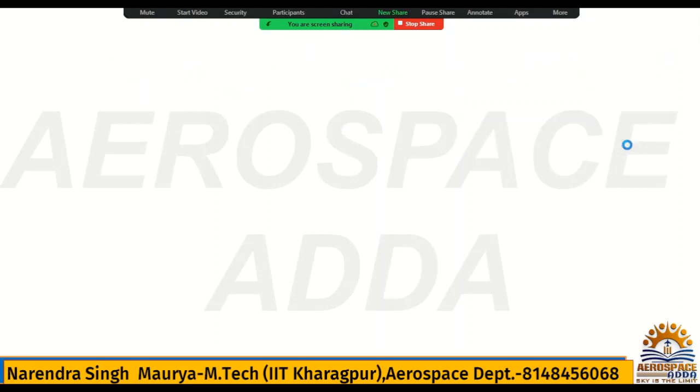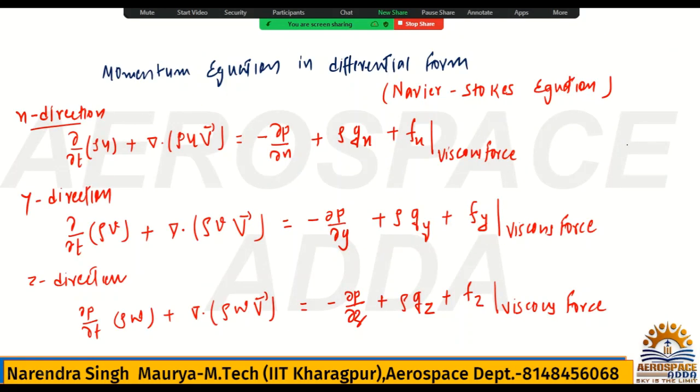So in this previous equation, this is the x direction, this is the y direction, this is the z direction. Okay, so in all three equations, if you apply what you have written, steady, so the time derivative term will be zero. If you are writing no body force, so gx, gy, gz will be zero.